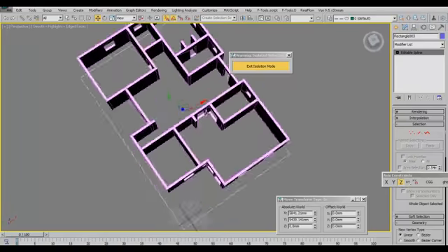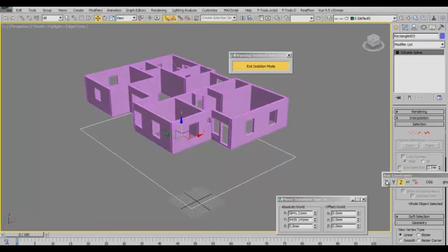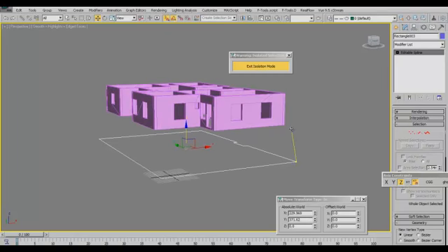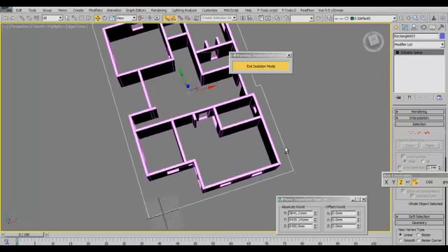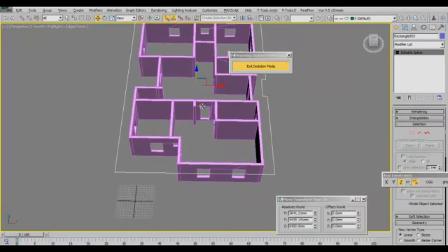We just want to move it along the Z axis basically, and not the X and Y axis. So we select the Z, then you say snap, use axis constraint. You turn this on, so when you snap, it only snaps in that direction and it doesn't snap in any other direction, even if you have the 3D on.